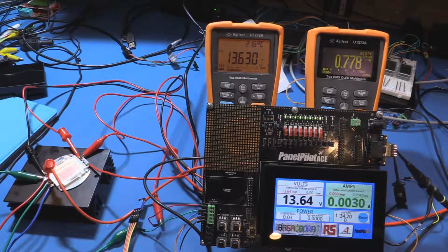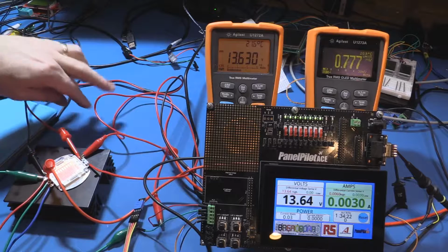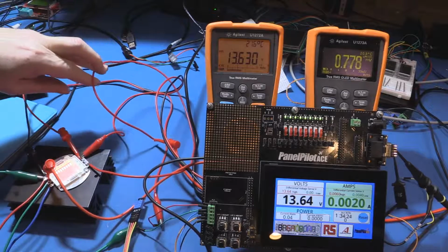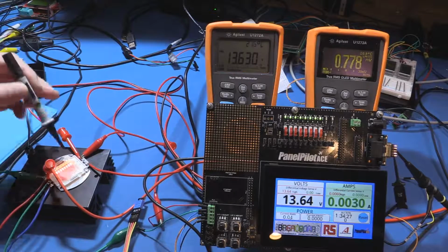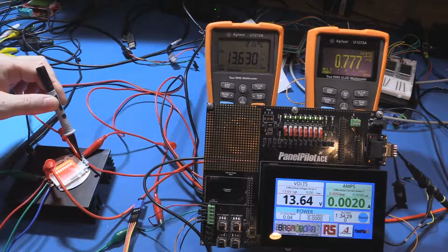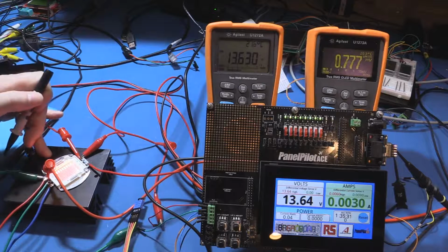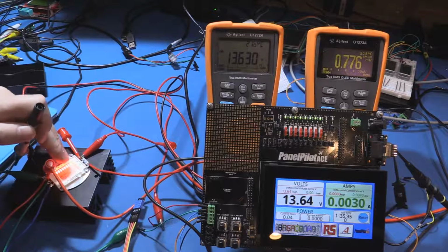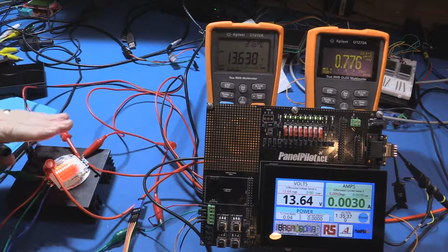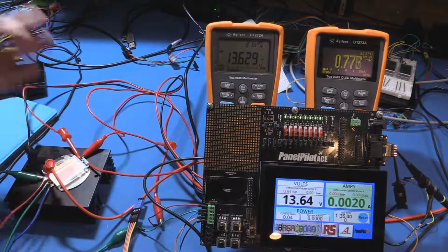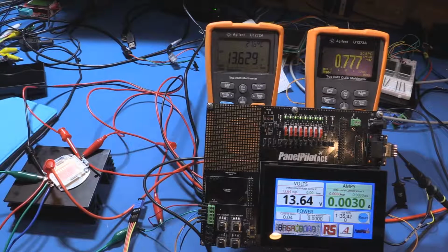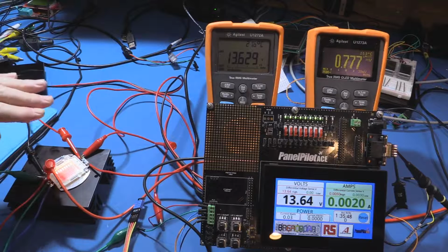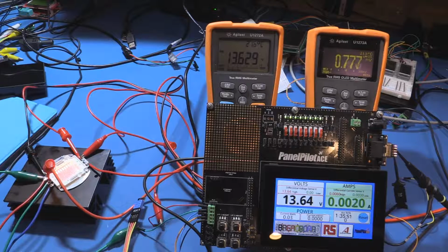The positive side of the power supply comes through to this cable, which is feeding into the positive side of this 50-watt LED, which is currently sitting on a heatsink. Now I've only got 2 milliamps flowing through this, and as you can see, even with just 2 milliamps, it's actually quite bright, and it's going to get a hell of a lot brighter once I start putting nearly 800 milliamps through it. But for now, I've just got it way down low so that we don't saturate the camera.